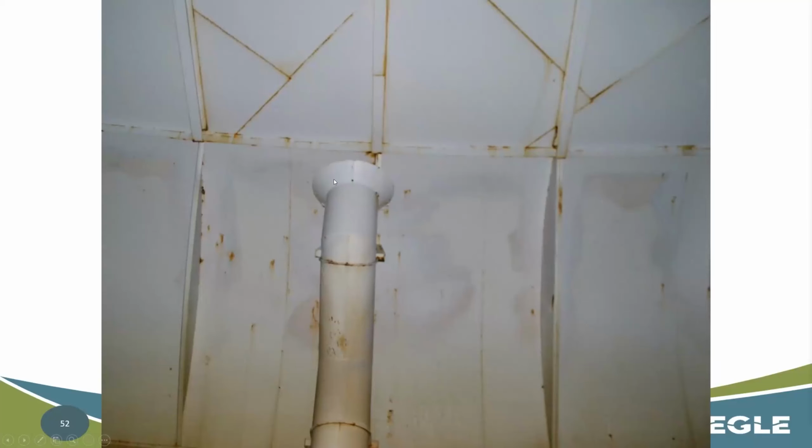Also, if water were to rapidly increase and continue going up, so it's not just spilling over the edge, you would actually get more water flowing out. So it's even better of a situation. You're not having that limited portion there like you would with a weir box. So that rounded, circular weir would be more ideal.